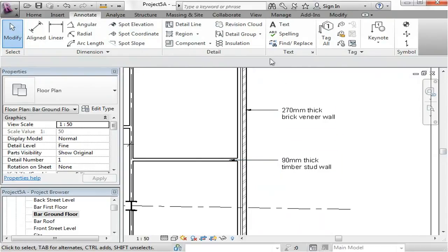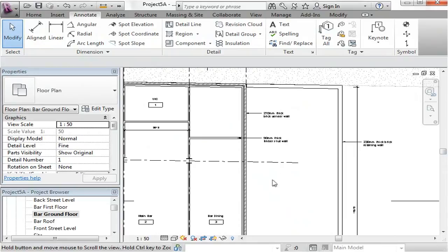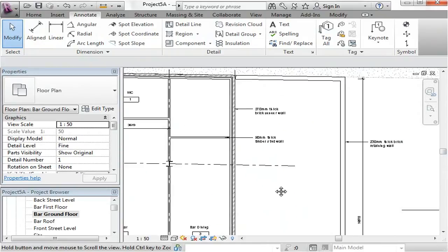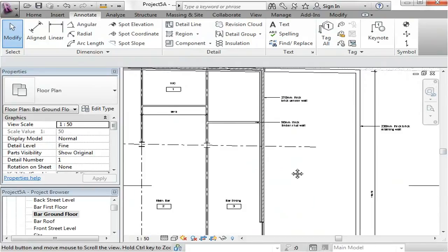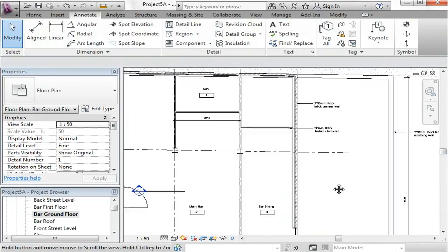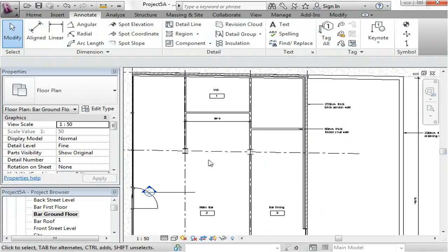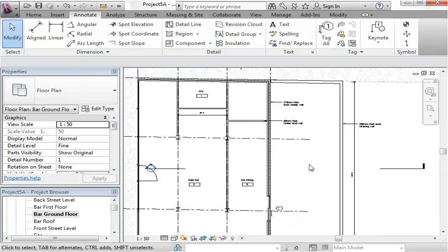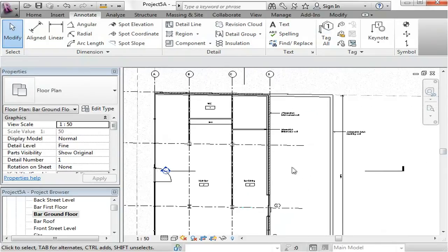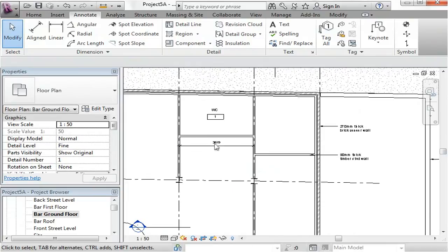So here the text is aligning, the arrows are finishing at the same place even though they do point to different places, and that's fine. So keep your text clean and neat, align them where you can, and try to avoid putting text everywhere in all sorts of patterns. And that's just a basic introduction to dimensioning and annotation. We will go further into annotation and some more detailing in the next tutorial when you start creating your detail drawings and putting some construction line work inside it.